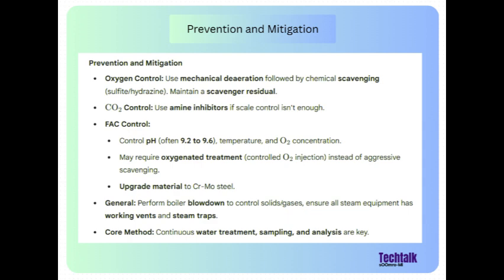Wow. So the very thing that causes pitting, oxygen, is needed in trace amounts to prevent FAC by stabilizing the magnetite. You nailed it. The poison, in tiny doses, helps maintain the antidote, which is the magnetite layer. That explains why the chemical monitoring has to be so precise. Living in that 3 to 7 ppb range requires constant vigilance.